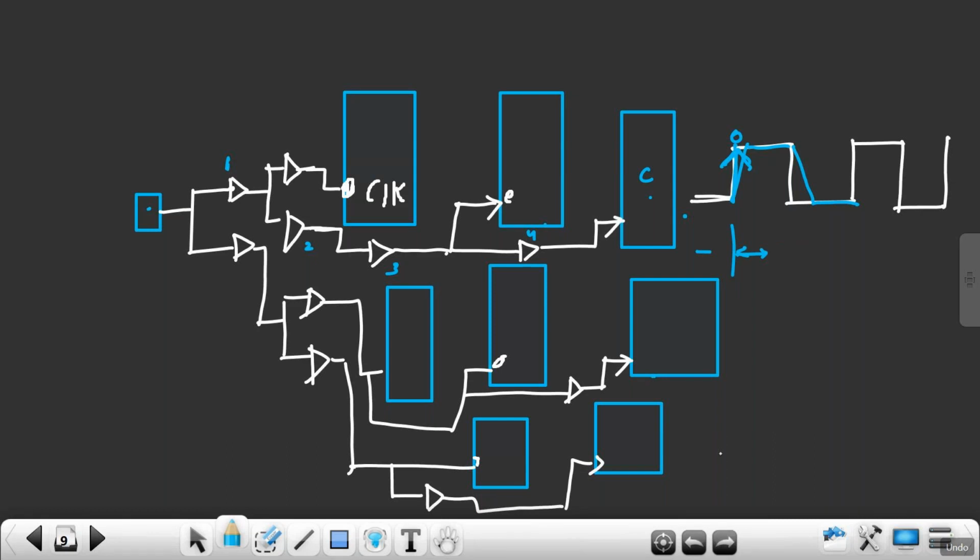So you also have some small delay, small transition. The same clock edge what you were getting at 0 nanosecond, I am getting to this flip-flop after 0.4 nanosecond. So this is called insertion delay. This buffer delay is called insertion delay. So my CTS tool should see that this transition is in the limit. First thing. For that reason only we are building clock tree synthesis. Main thing, clock transition should be in the limit.